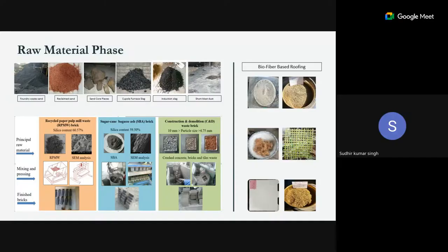Now, here comes the second point: are we using the waste as it is, in the form in which industry is dumping it? For example, slag. You are aware that there are two forms of slag which we can use. One is the slag aggregate, the crystalline form, and another is the granulated form. For granulation, you require some particular system. So is this system CO2 friendly, or am I putting some more energy into it? If it is energy intensive, that particular energy component I have to account for, right?